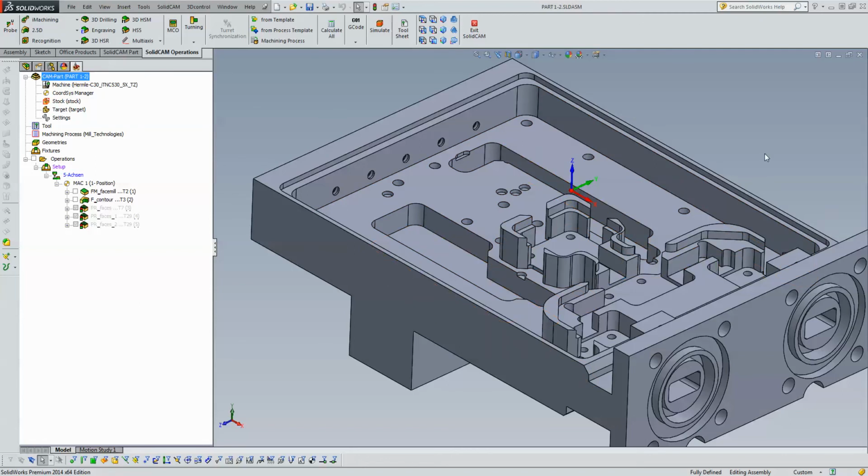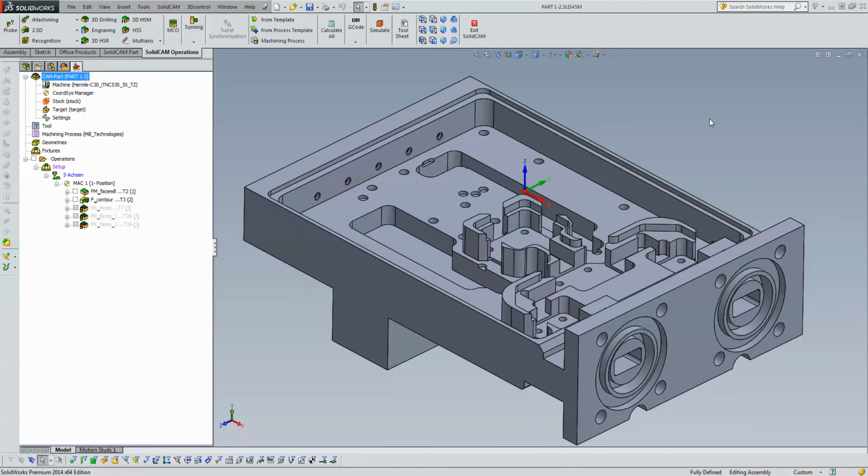This is very typical in the aerodynamics areas where we have different types of electronic housings that use these types of features. This is basically an electronic housing that many people may work on sometimes. Working on something like this, you need to do several different pocket operations or profile operations to get all of these down, and sometimes it makes it very hard to pick. So let's see exactly how I can do this using the option of pocket recognition.